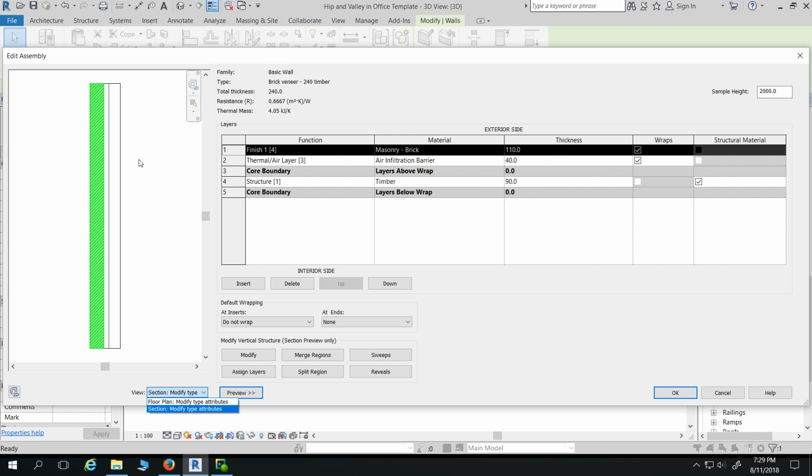Go RH then. So you've permanently hidden all the... whoops. You might have come down here by mistake trying to fix it and accidentally clicked apply temporary hide element. So just go to undo in the drop down. So go HR now. There you go. So you just click on wall, type, structure, preview, change that to a section.